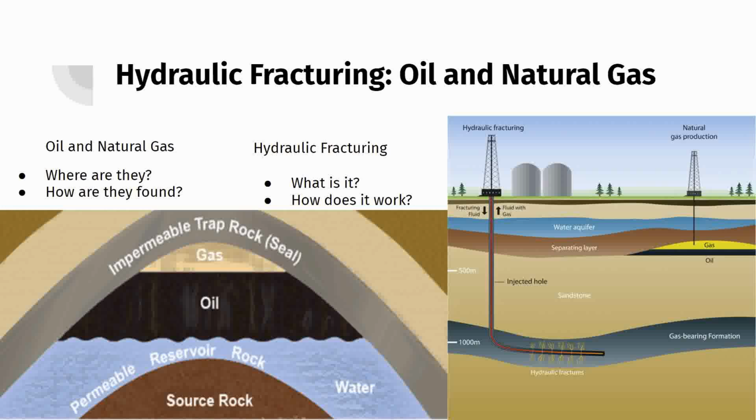These surveys can be done a few different ways, either by small underground explosions or the use of trucks with vibration features that send sound waves down into the ground. Geophones are what collect the seismic wave reflections, and that data is then used to make either two-dimensional or three-dimensional images of what's below ground.